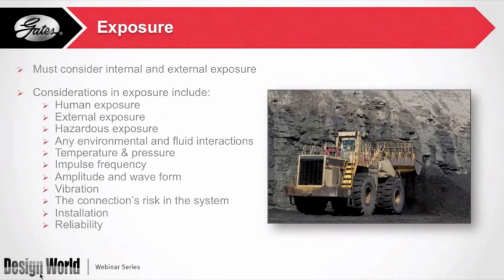Generally speaking, a permanently attached swaged or crimped coupling is going to handle impulse frequency better than any kind of bolt-on coupling. And then on top of the impulse frequency, we want to look at the amplitude of the waveform and basically your pressure signature to make sure that you're going to handle the worst case scenario of the amplitude of that pressure waveform.